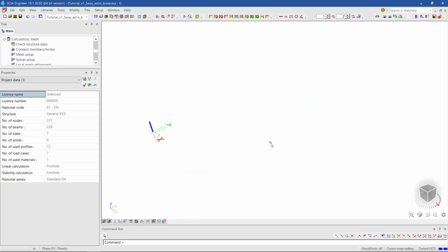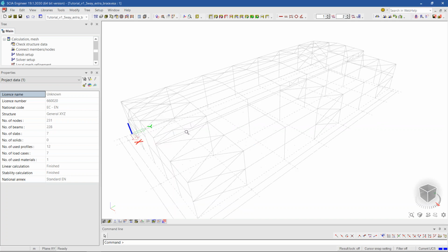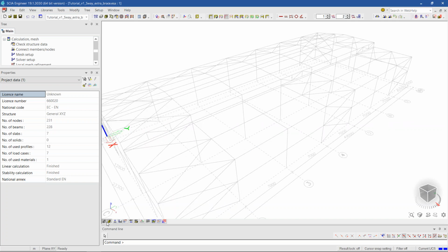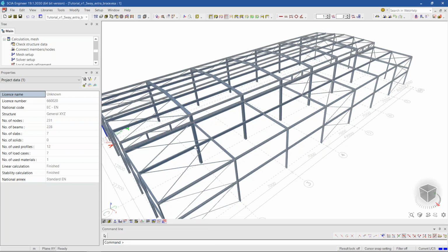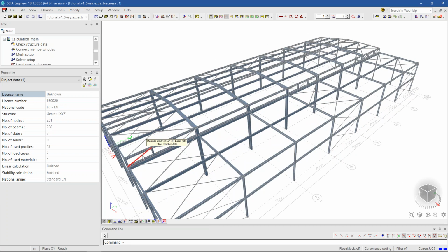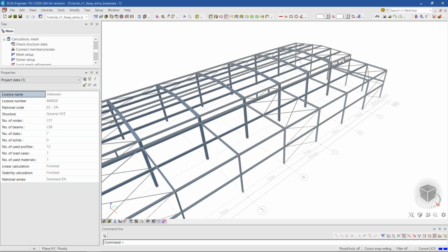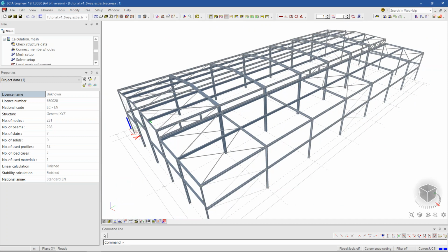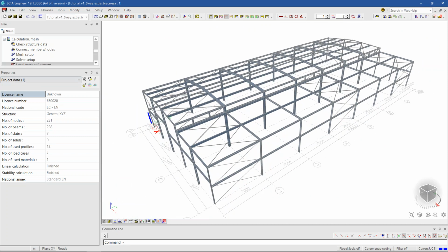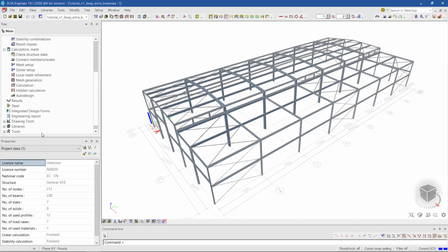But let's say that I don't have the possibility to do that. So what I've done is I've added, let's restore the extrusion of the member. So here I've added these bracing. And of course, they are really small. Maybe they're not so efficient. This is for the purpose of trying to get rid of that deformability of the structure.